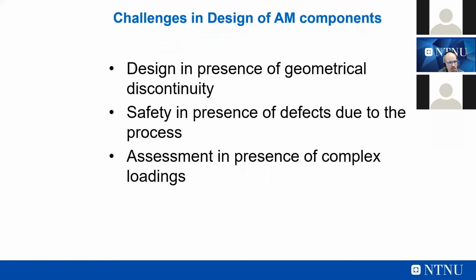So the main challenges that we have in designing against fatigue additive manufacturing components are the design in presence of geometrical discontinuities, safety in presence of defects due to the process, and assessment in presence of complex loadings, I mean complex triaxial or multi-axial loading.